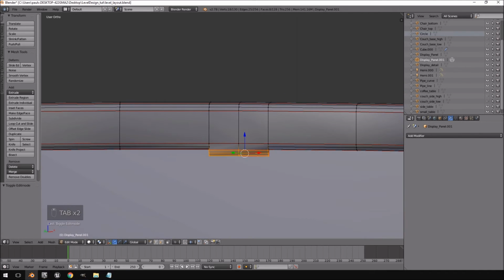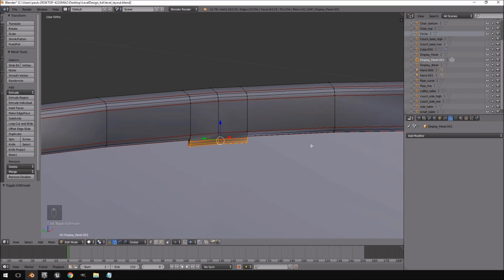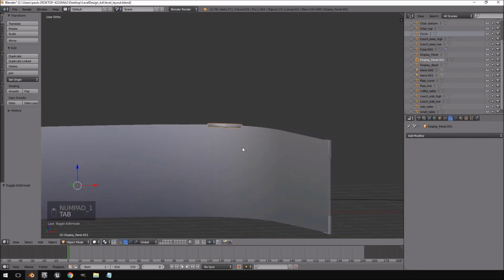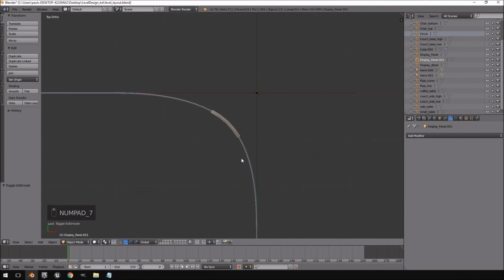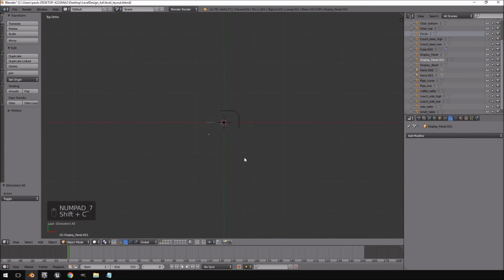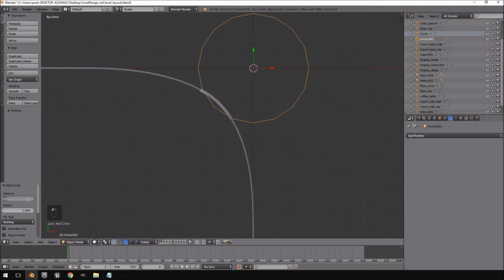And then they have a little red dot right in the center. Now, for the most part, people will think that that is a dot that is part of the model or part of the texture. You don't have to make it part of the texture. What we can do is go to the top view, hit Shift C to center, hit Shift A, and add a circle. We're going to do a fairly small circle, so 8 edges I think should be enough. There we go.